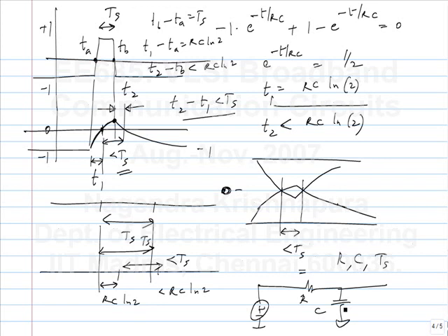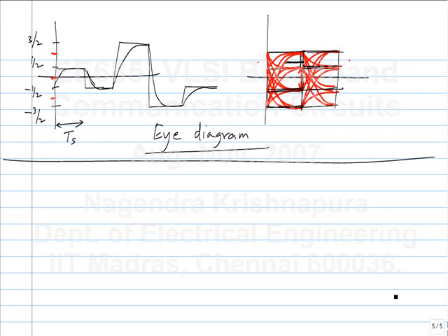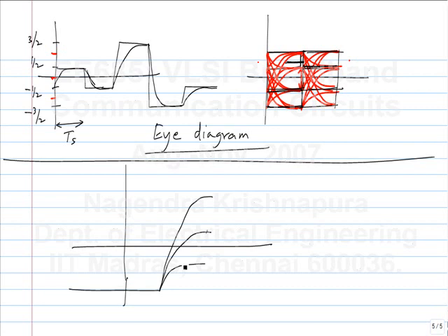I don't think that's the case. Why did you say that? That will not be the case at all, because if you have intersymbol interference, the initial condition matters, right? Maybe going from here to here is the worst case, isn't it? For the horizontal eye opening, let's say I start from here and then I go to this, or I go to the next level, or I go to the next one. So it could be that, and if I put the threshold at some point, let's say the threshold is here and here. So the threshold here could be larger, here could be smaller than that, and here could be the smallest. So that's possible. So it's not that the smallest one matters.